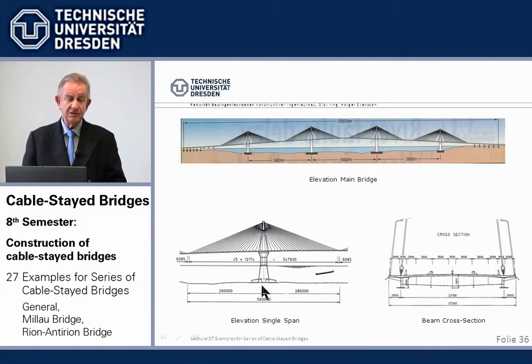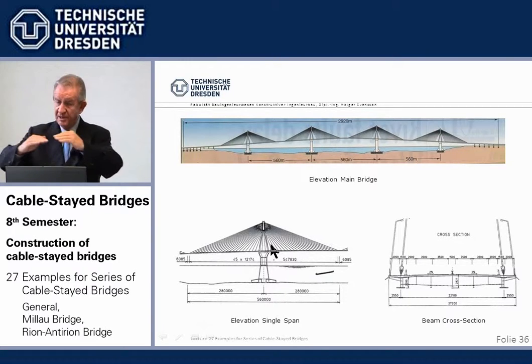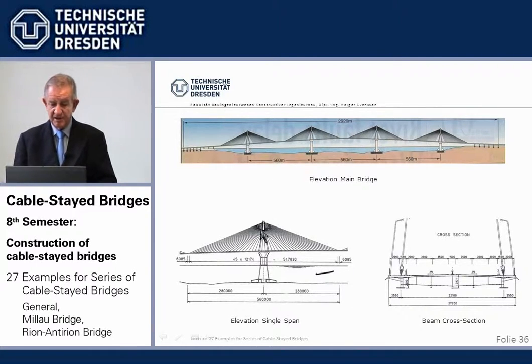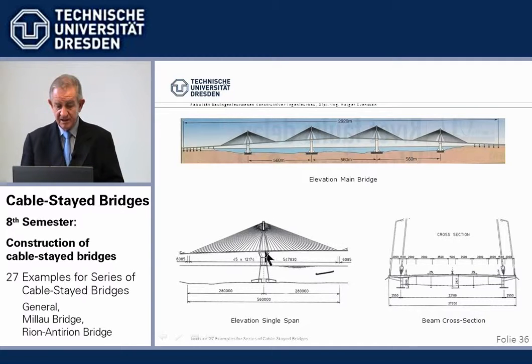And how now do we take care of our 2 main issues? Keeping the tower head in place and accommodating the beam movements. Keeping the tower head in place, we'll see it later also in some detail, we do in two ways. We have A towers again on top, similar as we had for Millau.